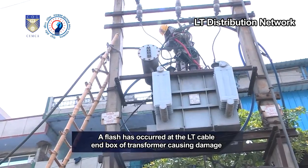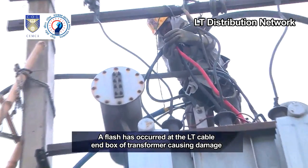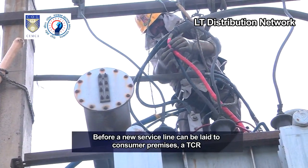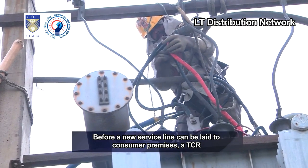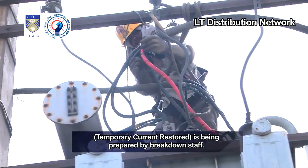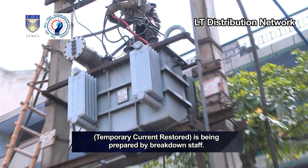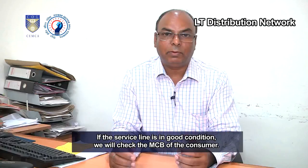A flash has occurred at the LT cable end box of transformer, causing damage to service line cable insulation. Before a new service line can be laid to consumer premises, a TCR, temporary current restored, is being prepared by breakdown staff. This is done by taping the insulation tape on damaged portion of service line cable lead.